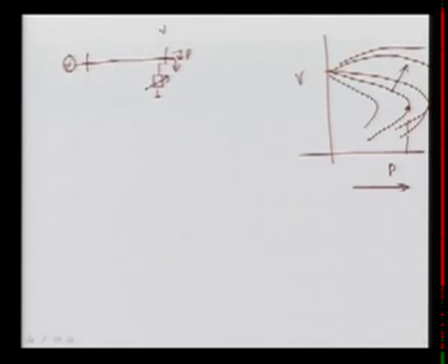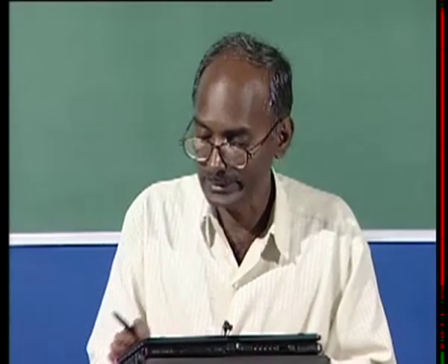If you observe lagging power factor here, then you can go for less loading. So here it is lagging, and this side is UPF, unity power factor. By providing reactive power support, we can go for more loading in the system, and then a higher voltage stability limit of the system. So with the help of a shunt compensator, we can improve the voltage stability limit as well, which I explained in shunt compensator. Now I am going to discuss the transient stability limit, and let us see how it improves.